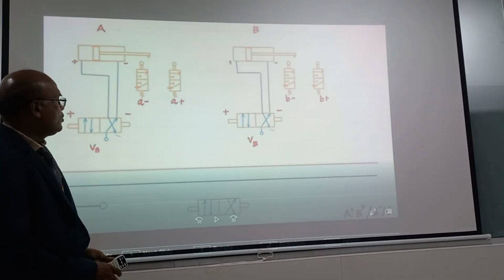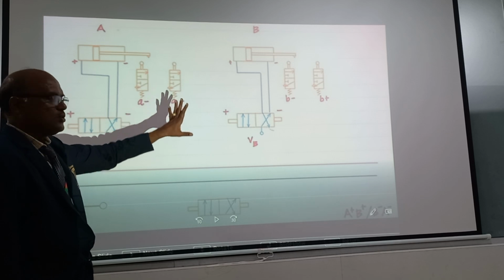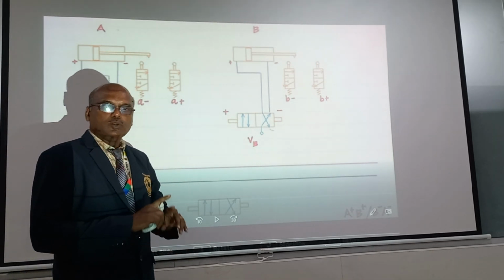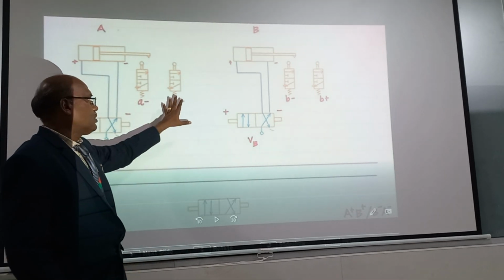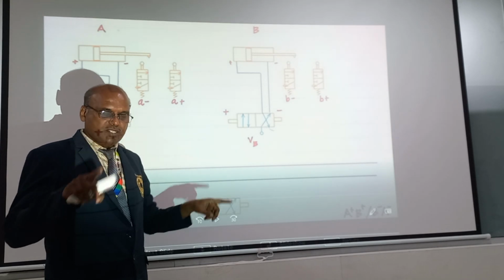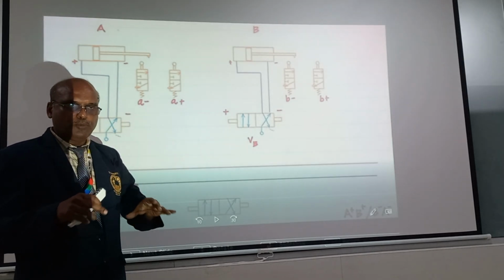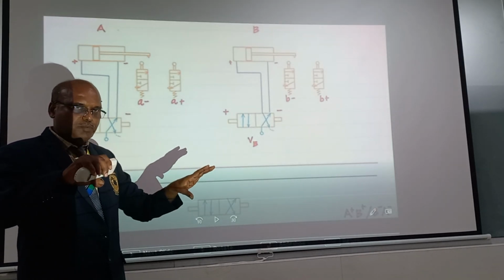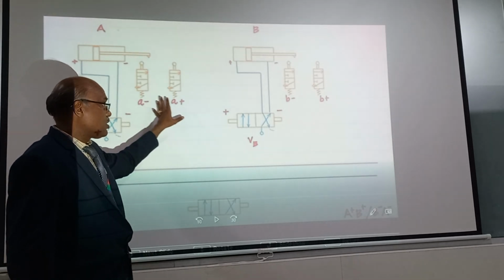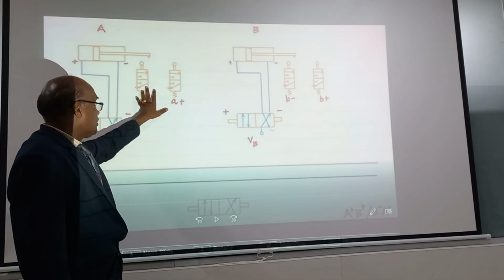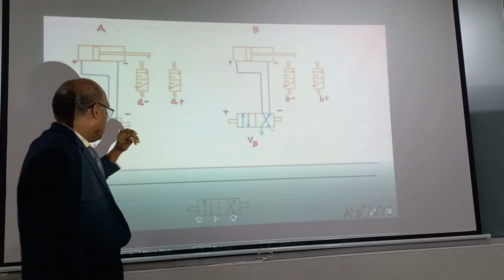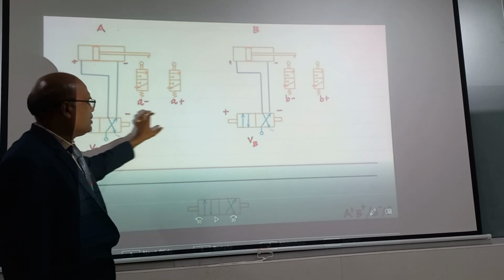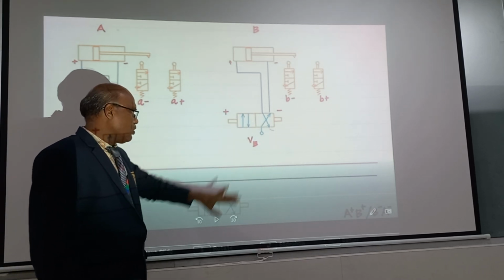Okay. Now initially you draw the basic elements. So in the exam, you draw in the landscape manner, take the landscape page, don't use portrait. Draw 2 cylinders, draw 4 limit switches and draw 2 direction control valves.